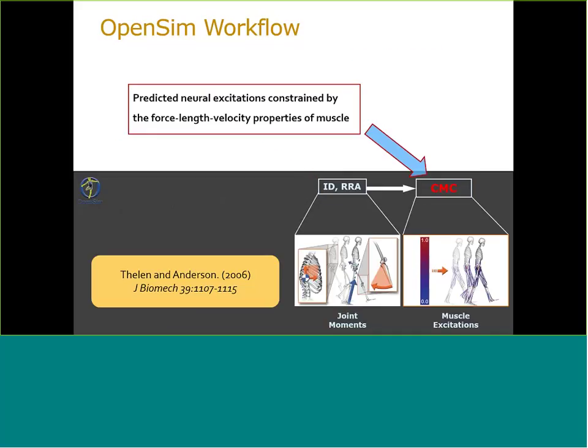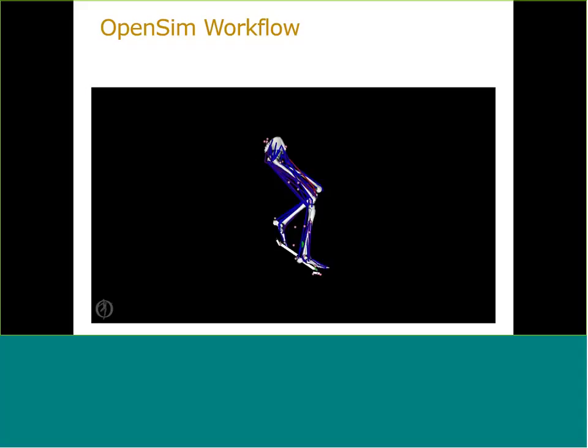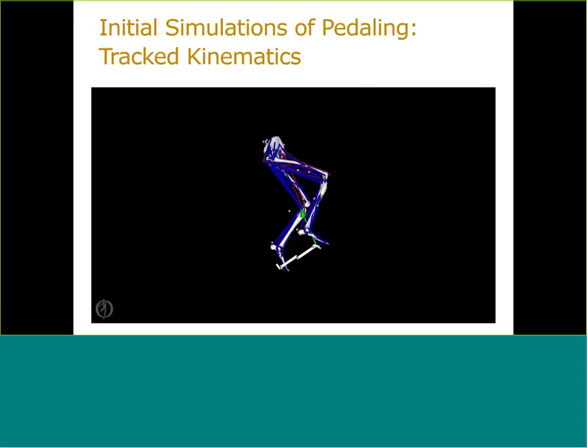Finally, we used OpenSim's computed muscle control algorithm to predict a set of neuroexcitations, constrained by the force, length, velocity properties of the muscle, that reproduce the subject's measured movement dynamics. Because CMC is also using a tracking PD controller, we also made sure that the resultant kinematics and residual forces were within the recommended tolerances. So here are our simulations of our initial attempts to generate subject-specific simulations of pedaling. And you can see everything in the simulation was consistent with our experimental data.